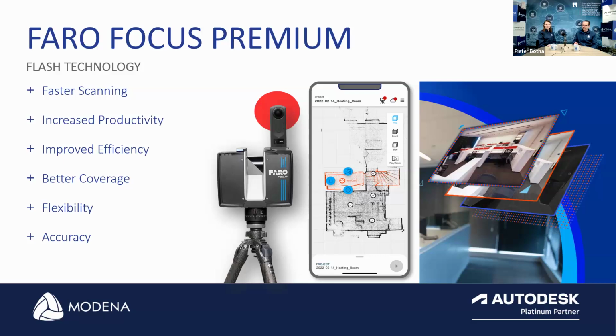Just to briefly touch on the Focus Premium with the flash technology, you can see the camera there at the top. The camera requires a mounting device, which we call the panorama mount, to attach the camera to the scanner. How this works is the camera will take 180-degree pictures on the panorama within a few seconds, and then the laser scans. The scanner scans in 28 seconds within the space of that single scan using flash scanning.